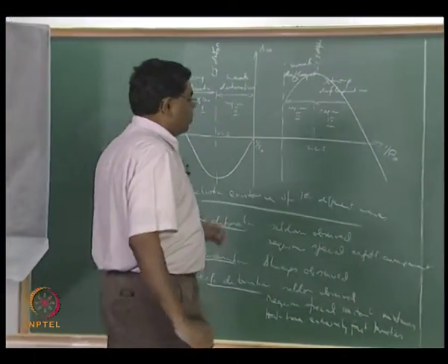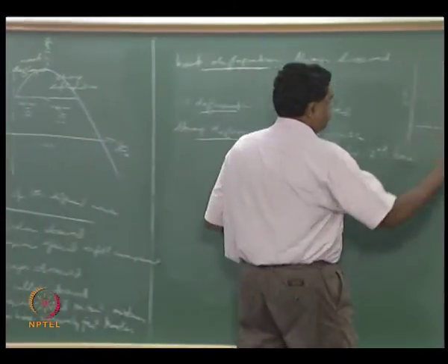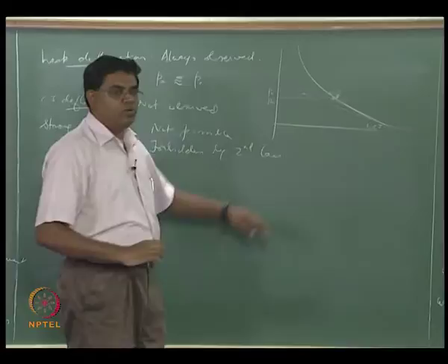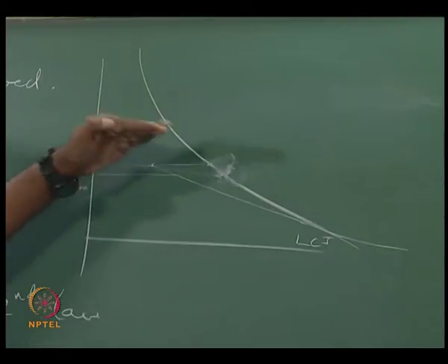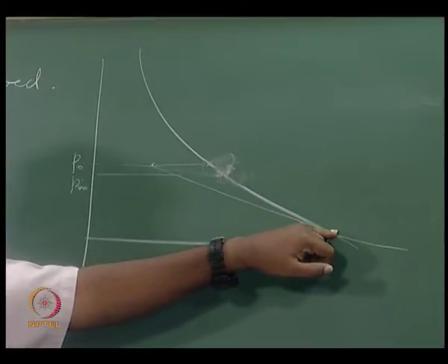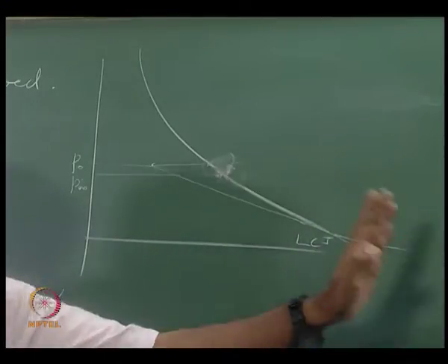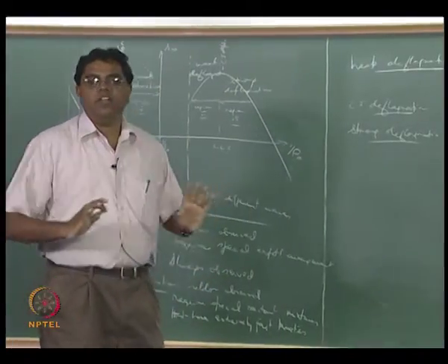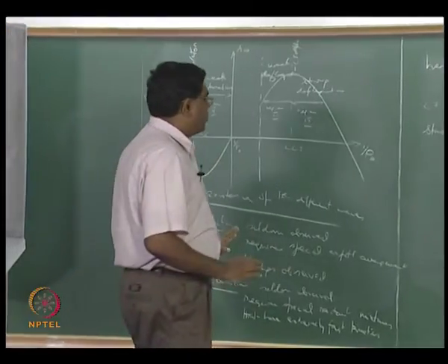So in reality, on the Hugoniot line we are pretty much confined to a region very close to where we started, P naught, and you do not even go all the way to the CJ, can't really go past it at all in reality. So most of your deflagrations are extremely weak deflagrations, that is the way I would put it.